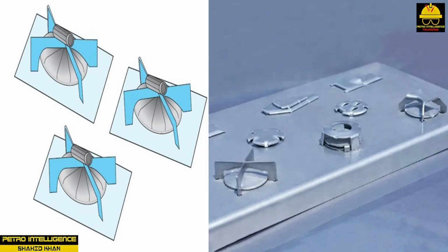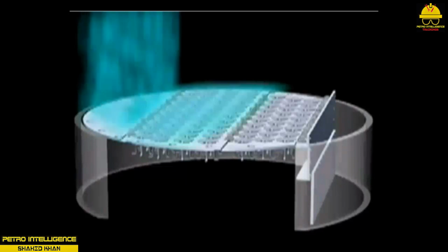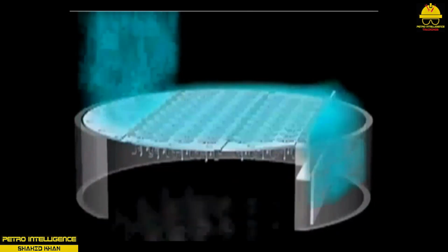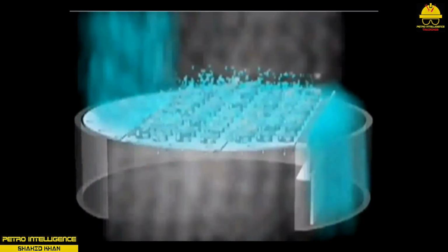Valve trays, as shown in picture, have simple, movable plates. Plate movement depends on process flow. This type of tray is more efficient over a wider range of flow rates than the sieve tray. Each valve is a metal strip or a small metal disc that lifts under vapor pressure. Flow is directed horizontally on the tray to produce good mixing.